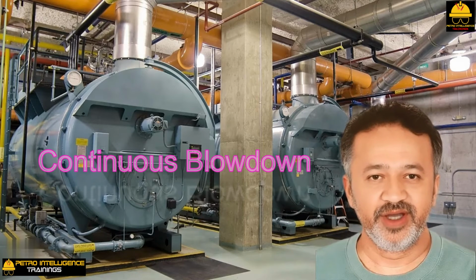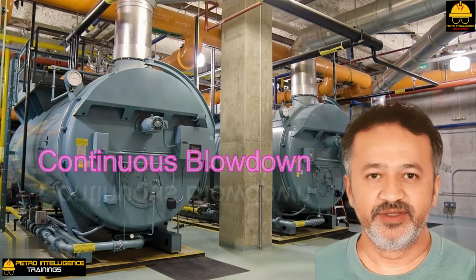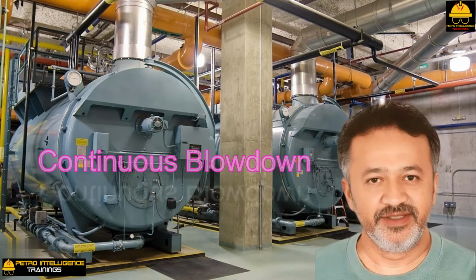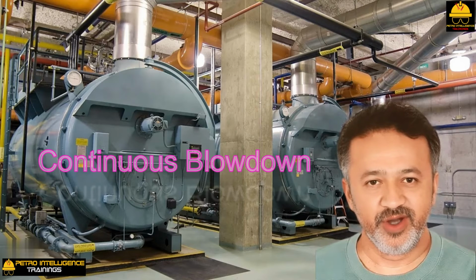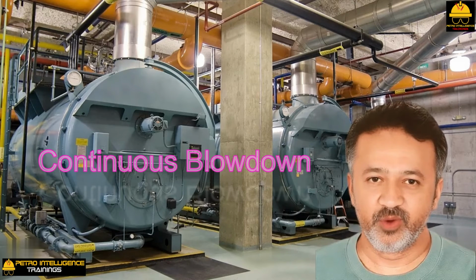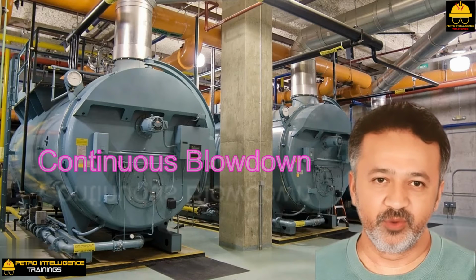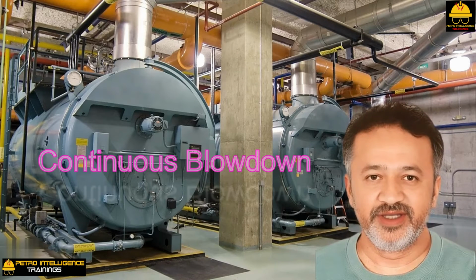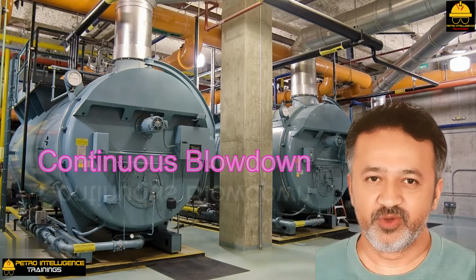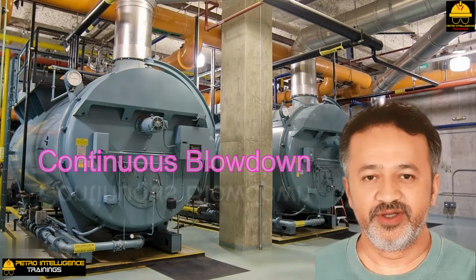The correct drain location is somewhat below the minimum water level in the boiler steam drum or in the kettle-type boiler. TDS in the blowdown is based on what the steam will be used for. A typical value is 1,500 ppm. If steam from a kettle waste heat boiler will be used saturated for heating, reboiling, or stripping, then the TDS content of the steam is not particularly critical.